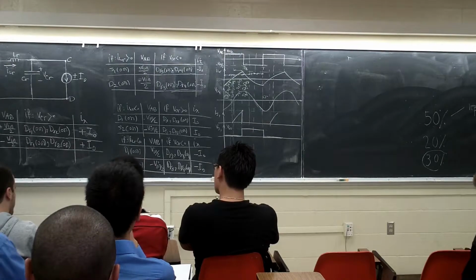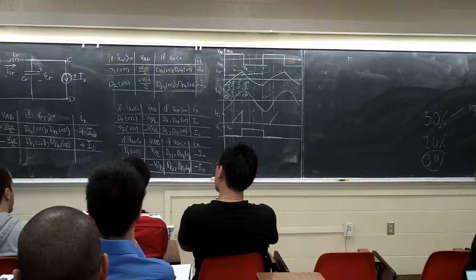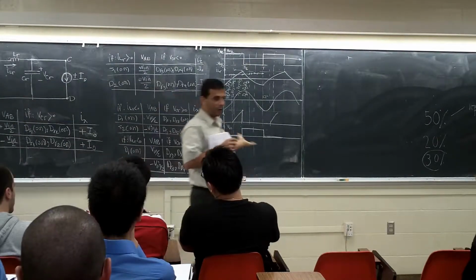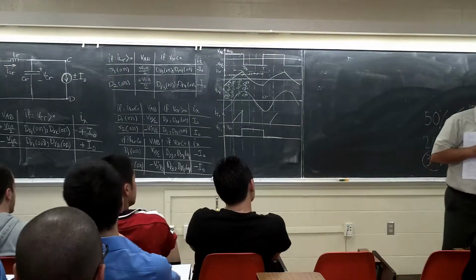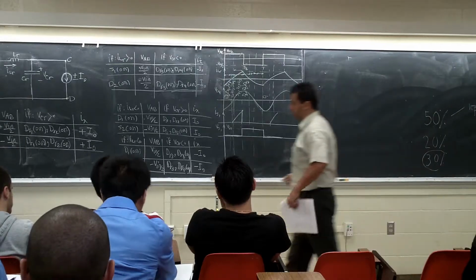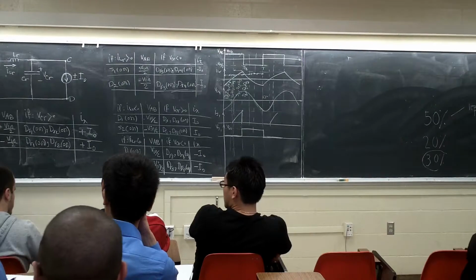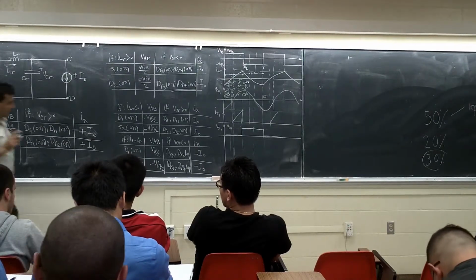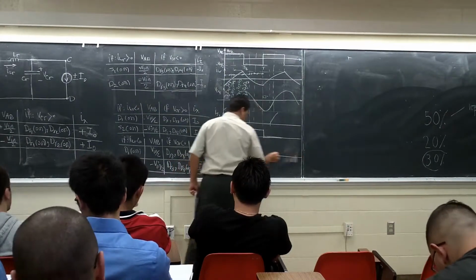You can check the same thing for this side also. You know what I'm saying? To see is there any soft switching on this side or not? Because these are diodes also, alright? They're going to turn on, turn off. It would be good if they turn on and turn off at either zero current or zero voltage, right? But we are focusing on this one because this is under our control. We are going to turn on, turn off, turn on, turn off, right? This is what we are doing. We can control here. So let's plot the Ix also.